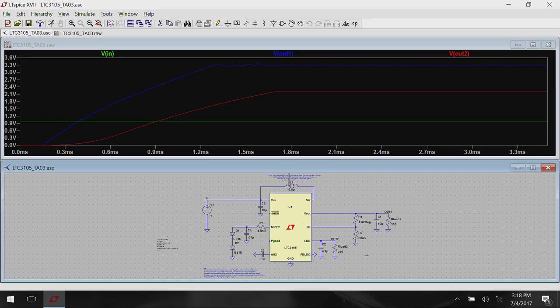This is the inductor which you have seen here, and this is the actual boost converter, and the current flowing through the inductor is giving you this wavy nature, and you want it to stabilize. Therefore, you wait until it stabilizes to a good value before you start using the output of the regulator.